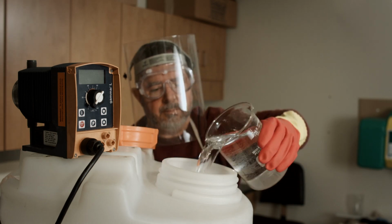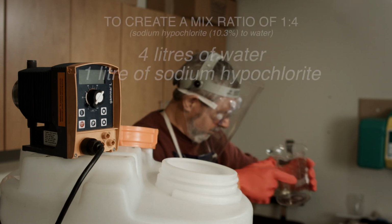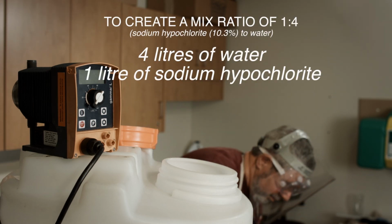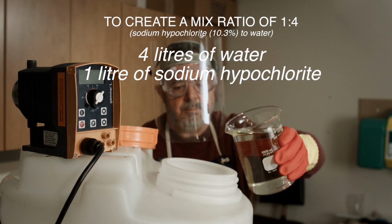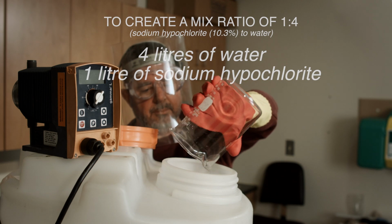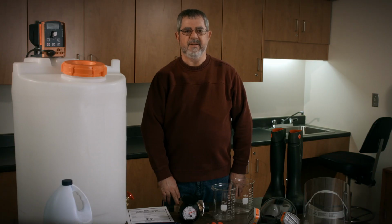To create our mix ratio of 1:4 sodium hypochlorite 10.3% to water, we measure 4 liters of water and add it to the tank. We then measure 1 liter of sodium hypochlorite and add it to our tank. We have now created 5 liters of 2% hypochlorination solution.